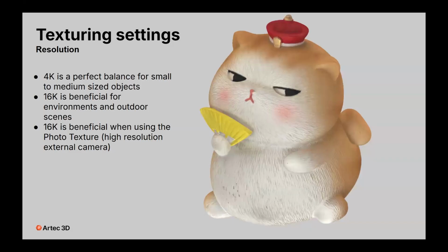Okay, so the first setting which should be set up is the resolution, because it's the mandatory setting for each of the texturing sessions. We need to tell the software in which resolution we're going to receive our final texture image. The most popular one for small to medium objects is 4K. It's a perfect balance between a large file size and good texture fidelity. So for most applications, 4K is usually the golden standard.